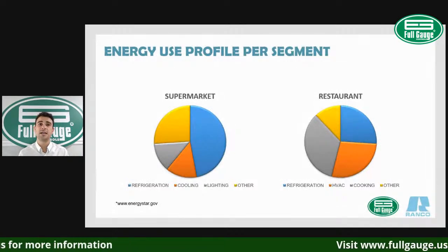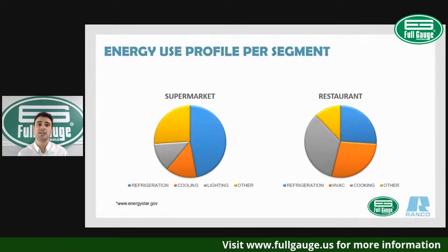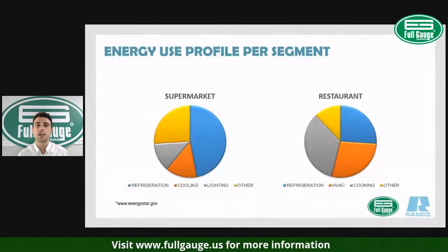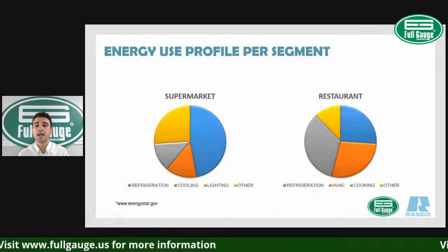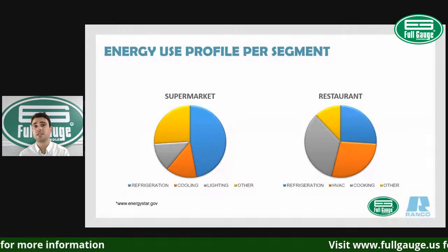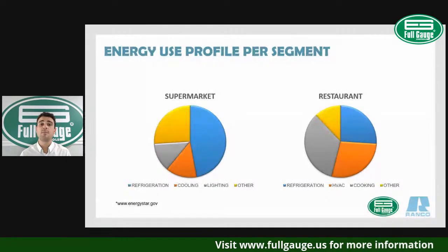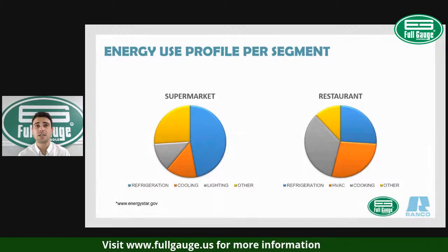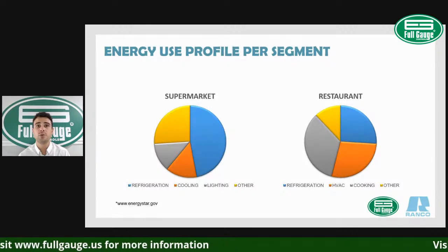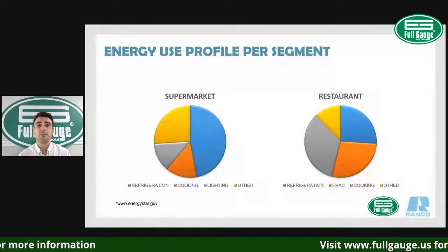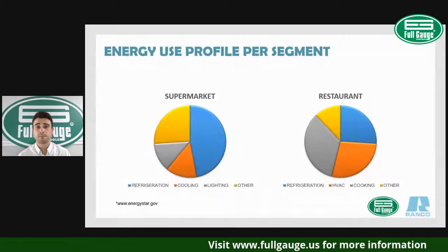We have studied the on-demand adaptive defrost technology in an application where we optimized 90% of the defrost cycles. So the adoption of those energy efficient solutions will allow you to reduce about 20% of energy consumption.